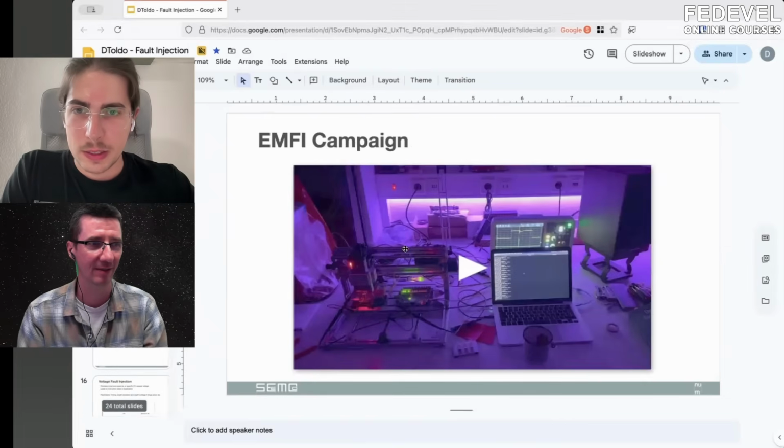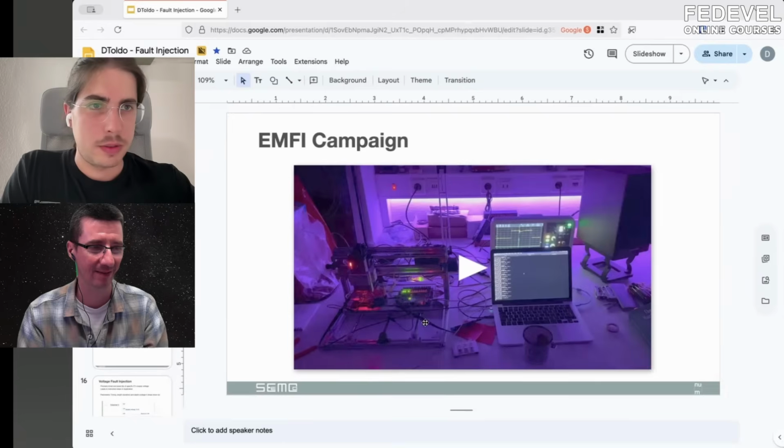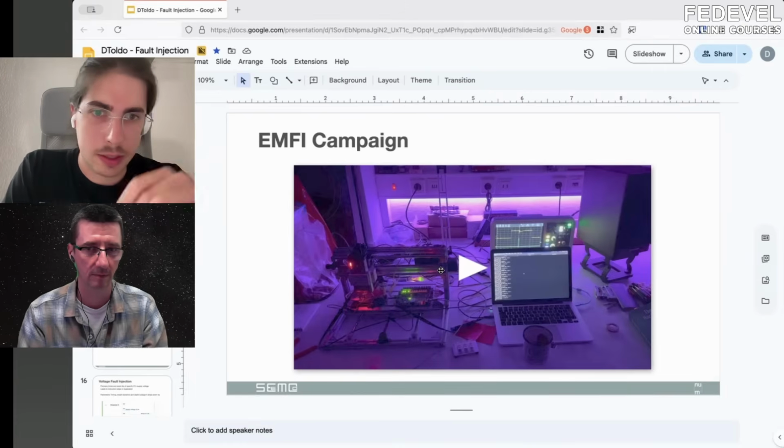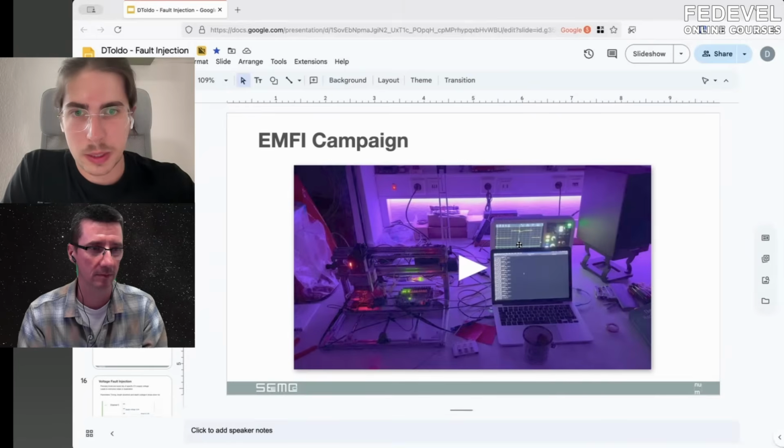Yeah, so basically, the platform is moving around. It's not much, but it's visible. It's 0.2 millimeters, and then you can see the LEDs of the timings that go on and off. For every attempt it will blink and it will run, and you will see the pulse in the oscilloscope, the high voltage pulses, which are 500 volts, and then the trigger line above, and the pulse will move around due to the different timings.